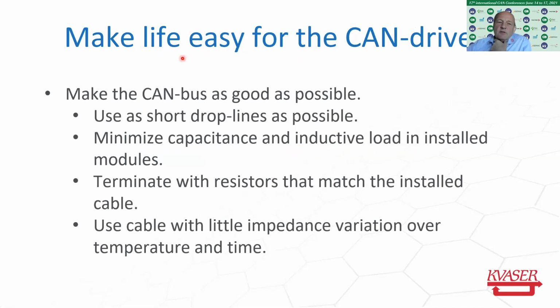So the first thing you should do is to make life easy for the CAN drivers, and that is to make the CAN bus as good as possible. To do that, the easiest way is to make the drop lines as short as possible. As you saw before, there are pros and cons.